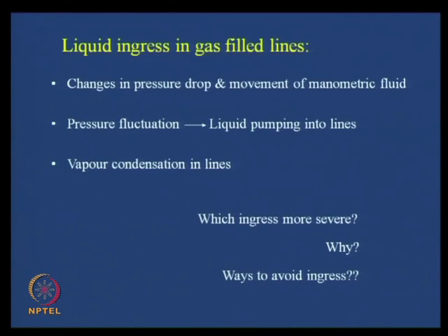But the good part is, see, in the manometer the movement of the liquid is much more vigorous. Okay. So, therefore, this pumping action is much more there. Here the diaphragm moves to a very small extent. So, therefore, pumping action is not so very high, and therefore, the ingressing of the second fluid into the manometer line is not so very serious also. Okay. But for differential pressure we usually always use liquid filled lines,